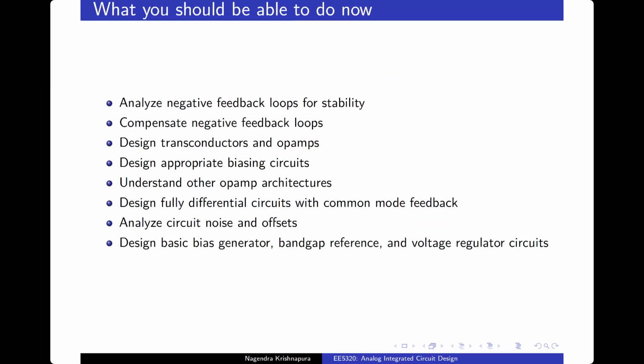Right, right. That you can do by simulation, right? Basically the idea is, those things, the cascode bias and so on, you have to adjust based on simulation. Of course, in the assignment, you have just one value. In reality, you have to make sure that it works across process and voltage corners and so on. So you have to generate that voltage so that under all the conditions, as the temperature varies over whatever range, as the process varies, and VT itself will vary even with process, even without body effect, the transistors do remain in the desired regions of operation.